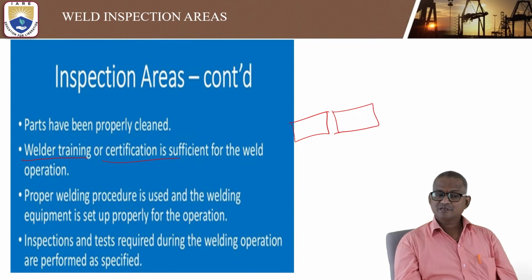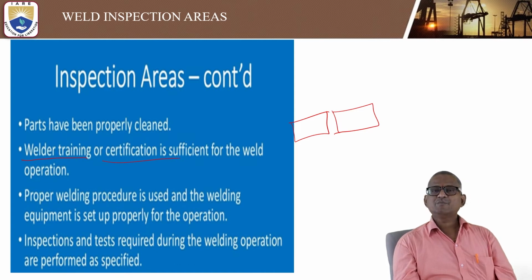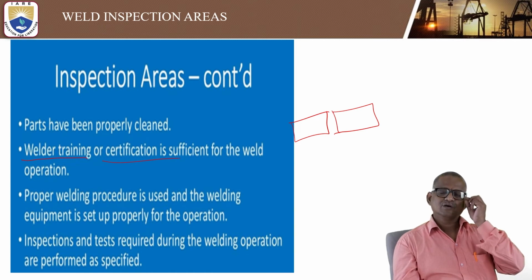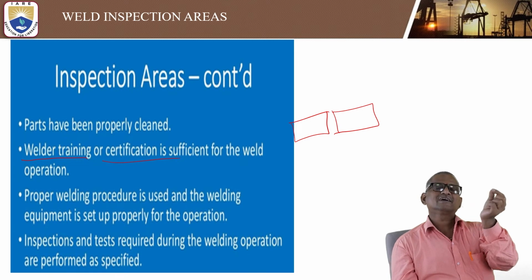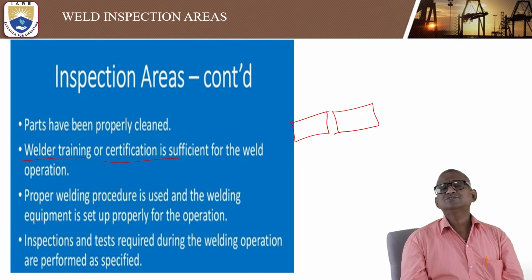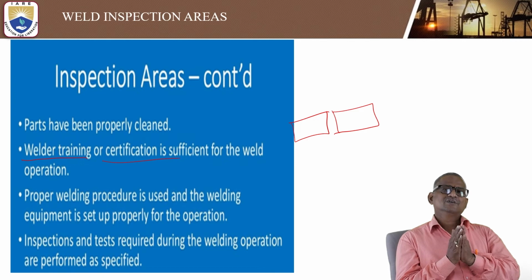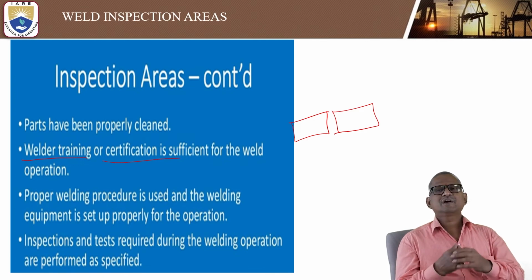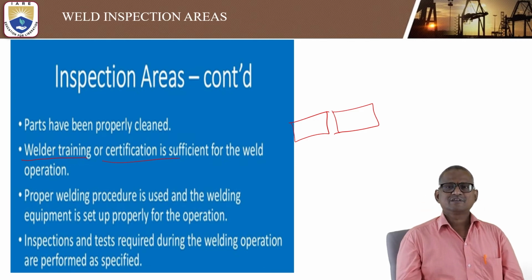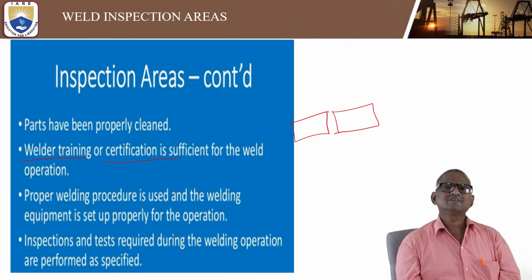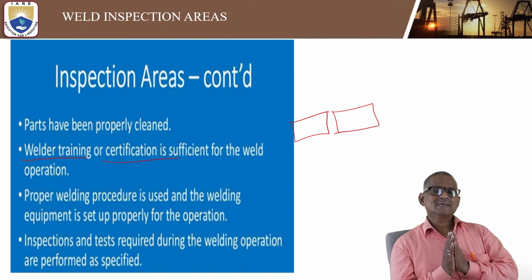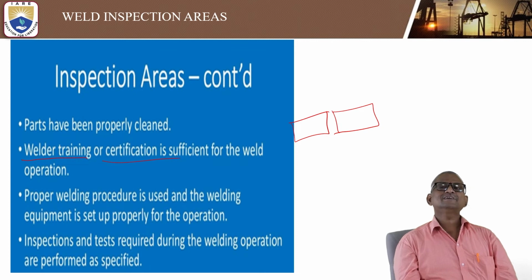Sometimes, traditionally, there is a problem when a student gets a problem in the eye, and it has to be removed because a spark fell on it. That is why we should take precautionary steps. You should wear the apron, goggles, hand gloves, and all things should be considered while performing welding. So initially you should take training. A welder can give proper training for performing good quality work.